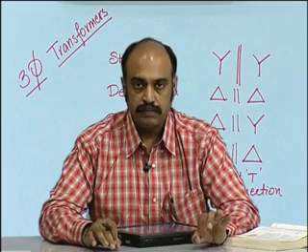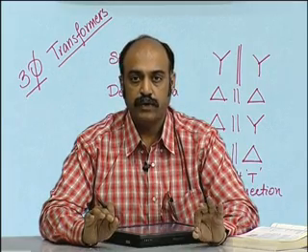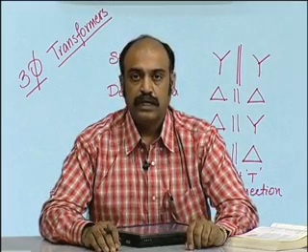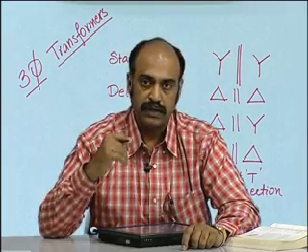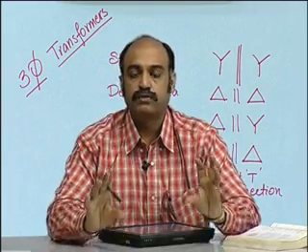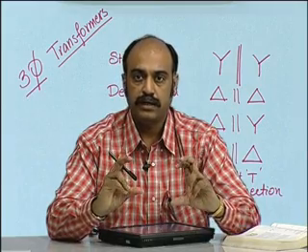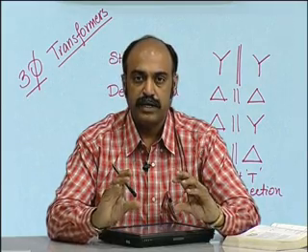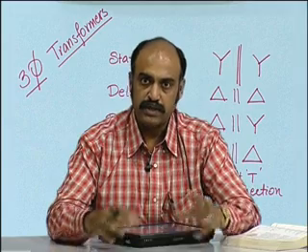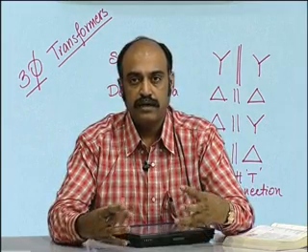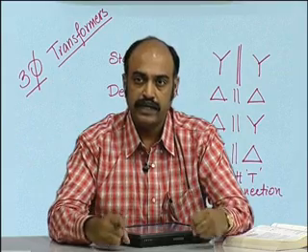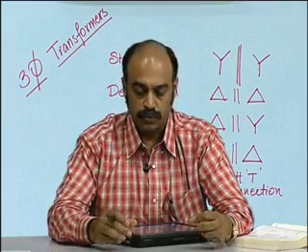It uses the same principle, that is the Faraday's law of electromagnetism, which is the induced voltage is equal to N times d phi by dt, that is the flux which is there in the core. It is composed of three independent separate single phase transformers connected in various topologies. These three single transformers are then combined into a single core.